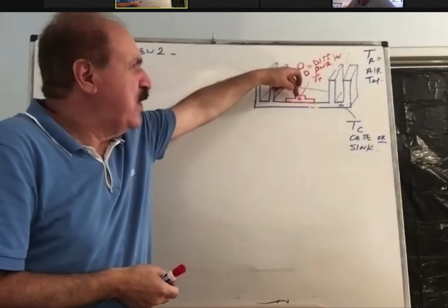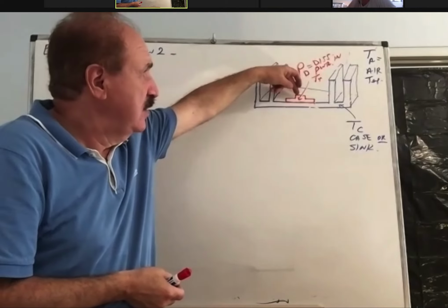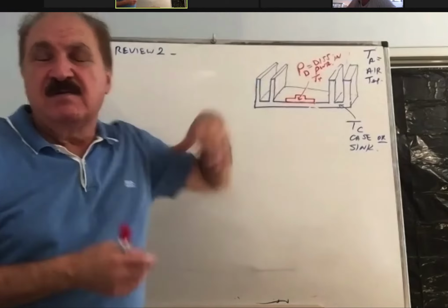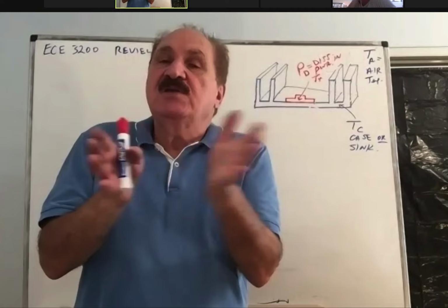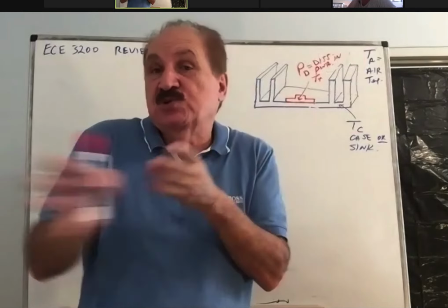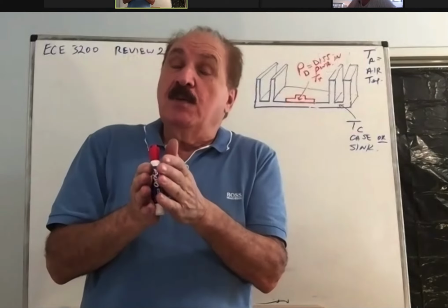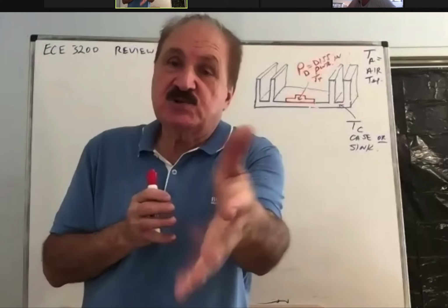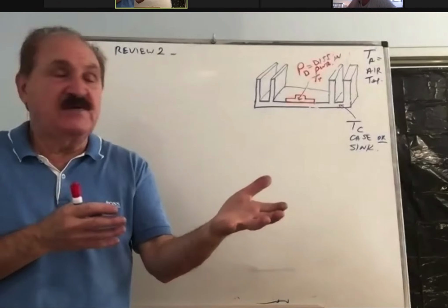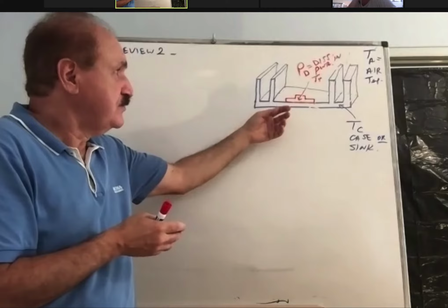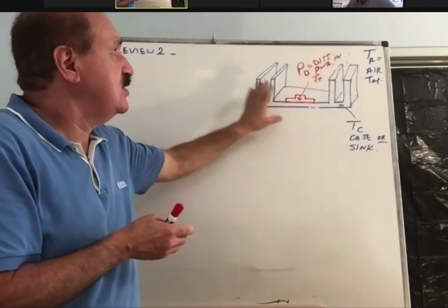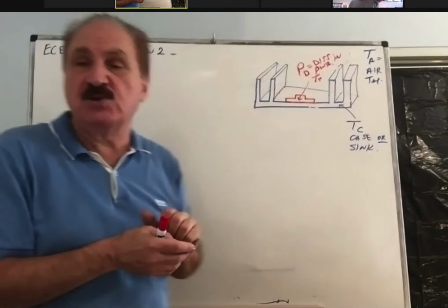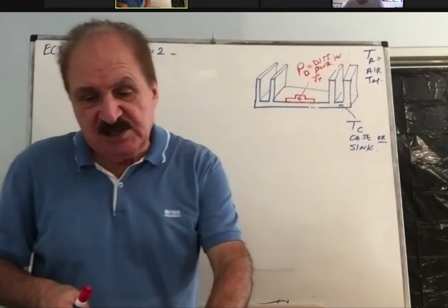Of course, a very small part of it will go into air. Well, it's just like a high resistance, low resistance. Heat always prefers to travel through the most conductive path as opposed to the high resistance path. So the heat will transfer to the sink and give that energy back into the air, and at steady state,